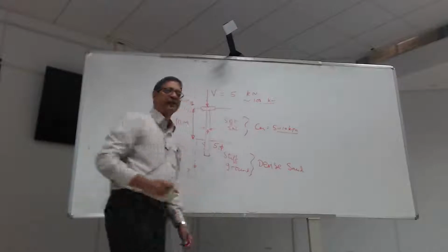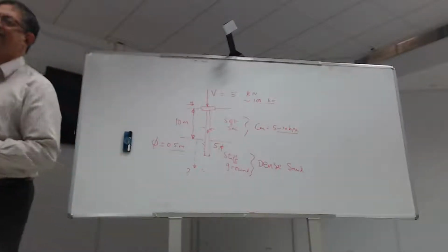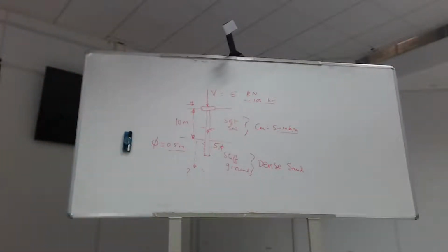Now again, numbers matter here because I'd always use the example of toothpaste. What would be the undrained shear strength of toothpaste, you think? Every day we use it, so we know you can squeeze it, it'll come out. But yet on the brush, it won't flow. So it has clearly got some strength, right? So the toothpaste would have about 1 or 2 kPa.